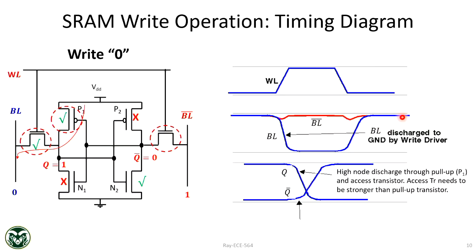If you don't want to design an ultra-fast SRAM, then you can wait for things to settle down, but you can turn it off even a little bit earlier as well. Industry does that. That's why they have different grades of SRAM. If you just type in Amazon, there will be high-speed SRAM, ultra-stable SRAM, low-power SRAM, different types. It is all made of 6 transistors like this, but you just have to optimize your timing and other things based on that.